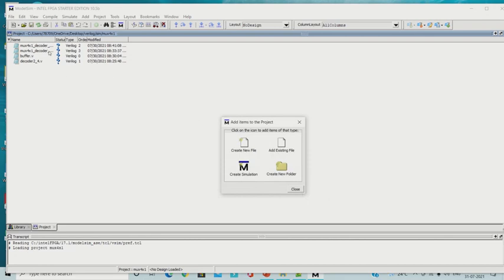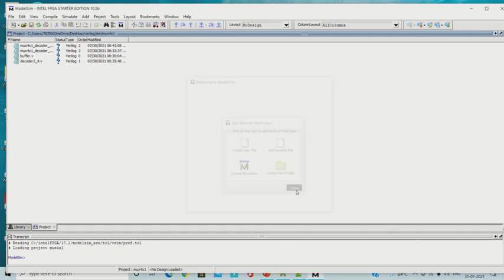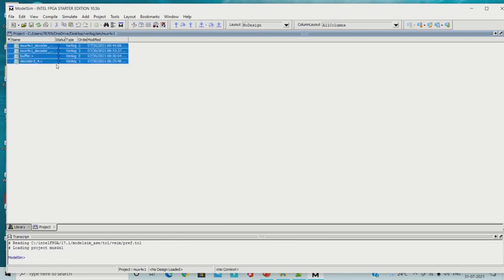now I have added 4 files. One is for TB. The second is the main module, which we are going to implement, and then the instantiation modules. Okay, then you can close it. And now we have to come back, as the status will be unknown. Like the compilation here is not done. So first we have to compile all these.